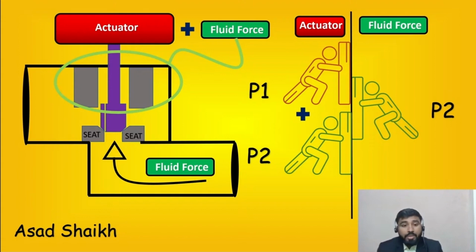Now, why am I telling you this? A lot of times what happens as engineers is, you give a requisition to a particular vendor. The vendor definitely has to save cost. He would not see any clause in your data sheet saying that there are going to be some solid particles. You missed mentioning that clause, and he gives you a balanced design. Now when it gets to the plant, that hole will get stuck and your valve will not function properly. It will not close and you will have an extremely high leakage rate.